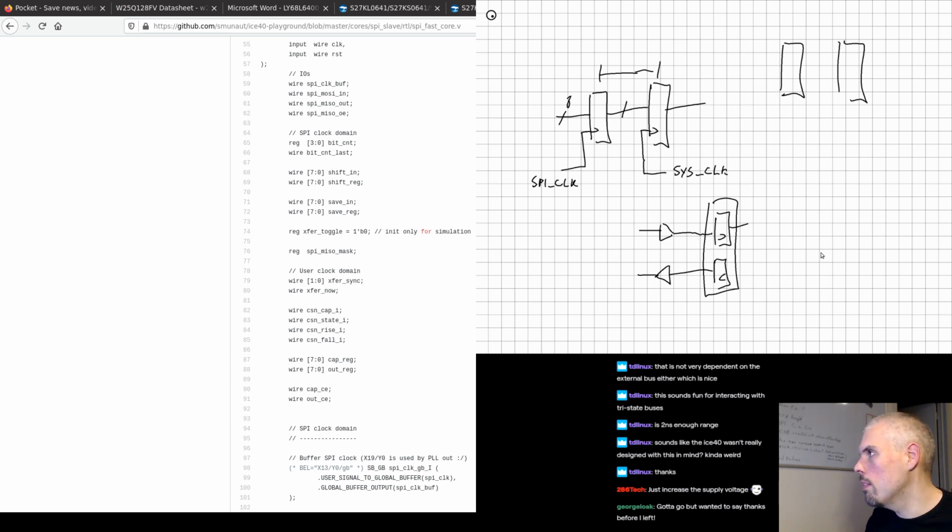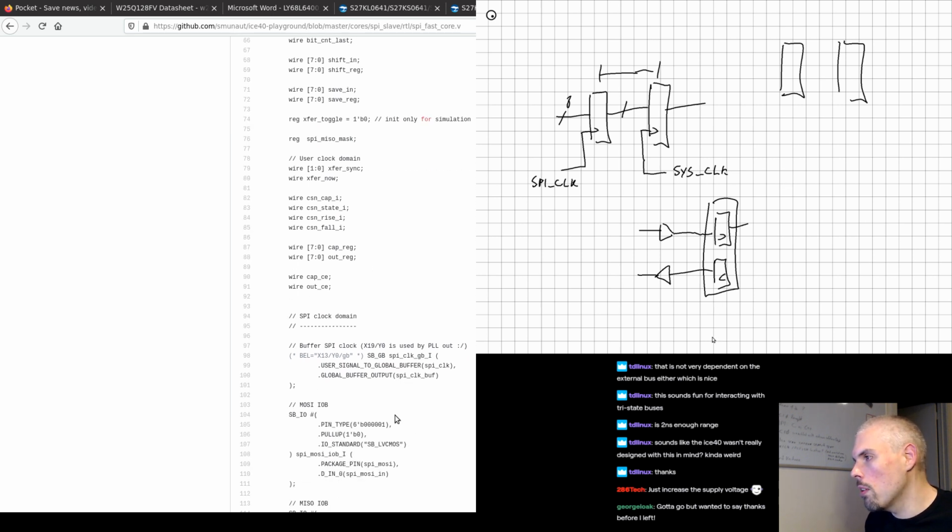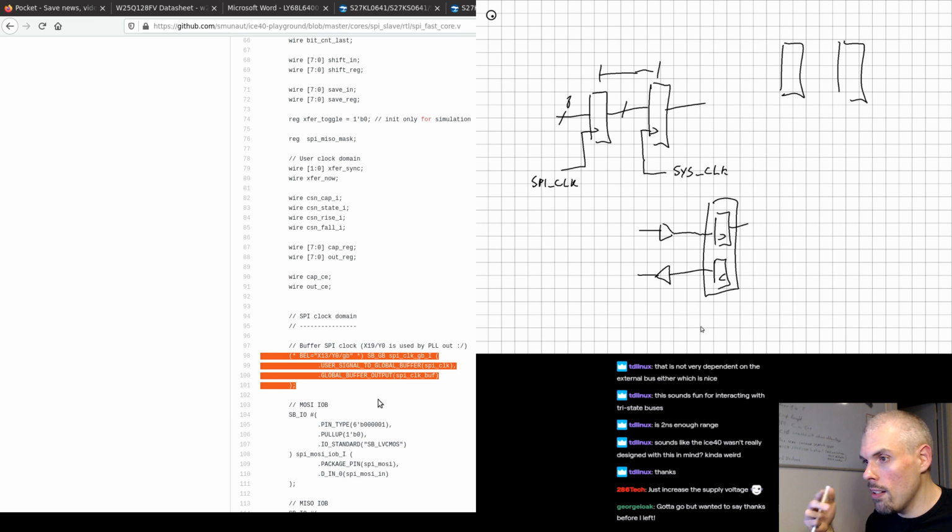I hope, Peter, that that kind of answered your question about why I had to do that. And so, yeah, among other things, I also locked like the input global buffer so that the clock delay between the external version of the SPI clock and the internal SPI clock is also fixed and stuff like that.